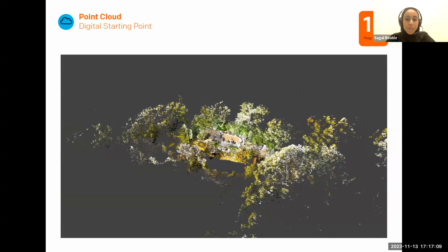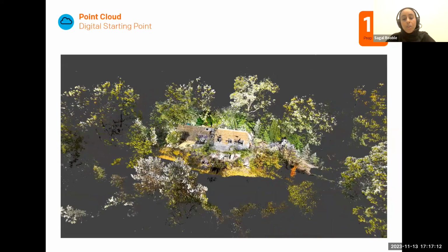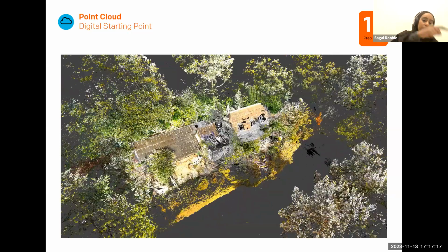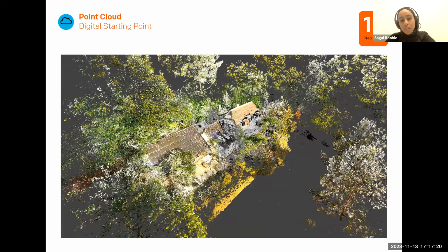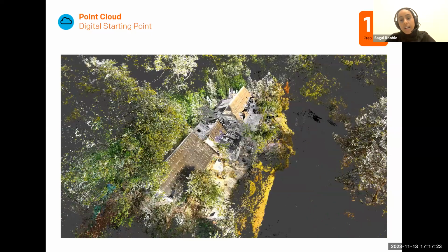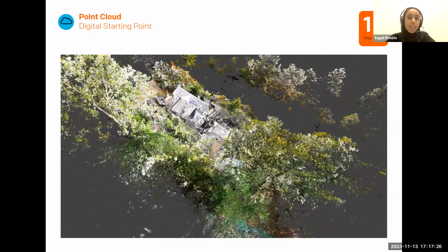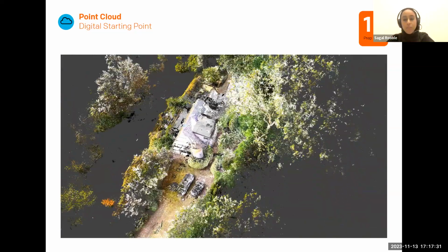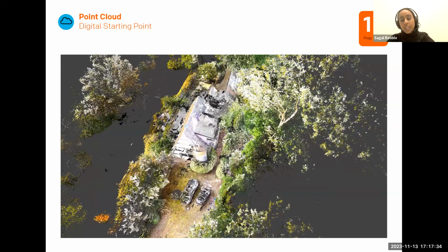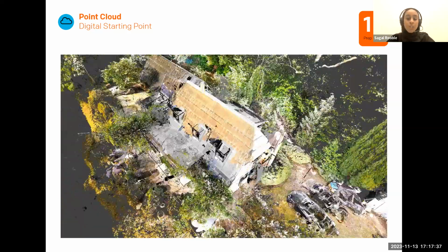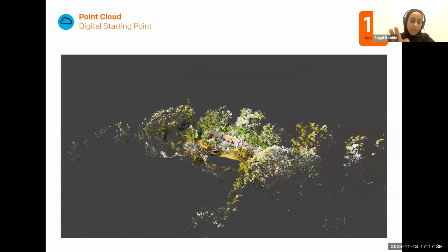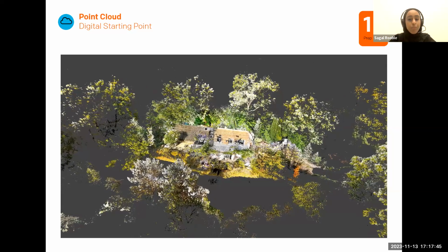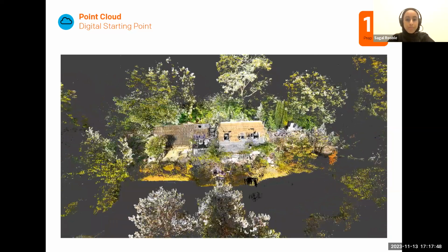And this is just a video to showcase what happens. That camera that you see on the tripod, we basically went around this whole building, and we were able to capture this asset. And the cool thing about the point cloud is that it shoots these laser points in a 360 format, so it will pick up anything that it could see within its vicinity. Once all the capturing is done, it's all put together, and you get a model full of points which can be used to model.